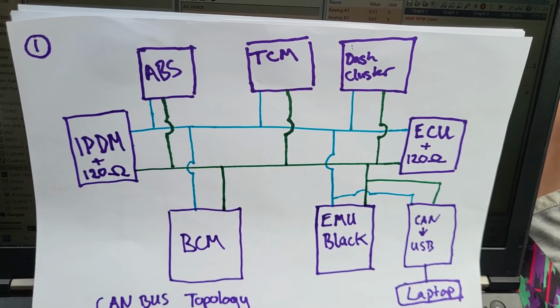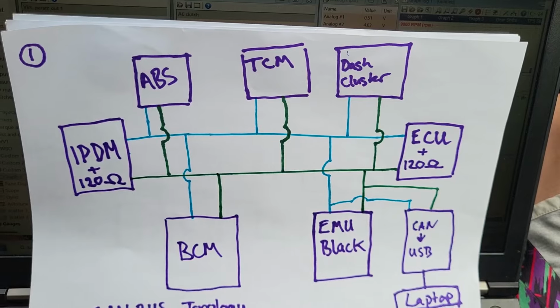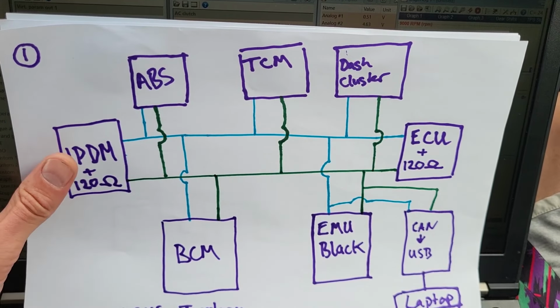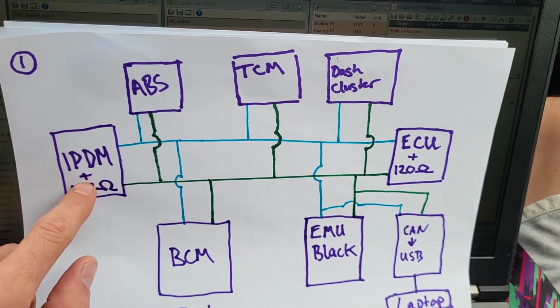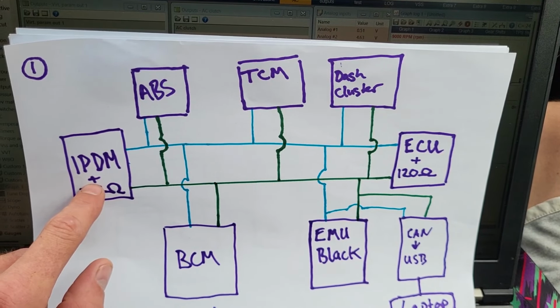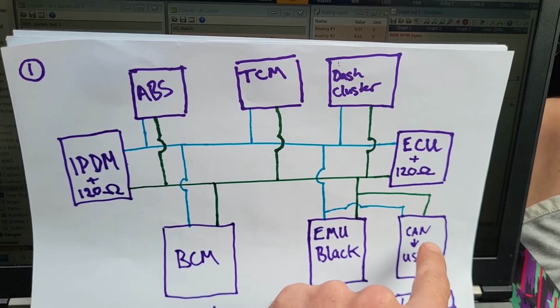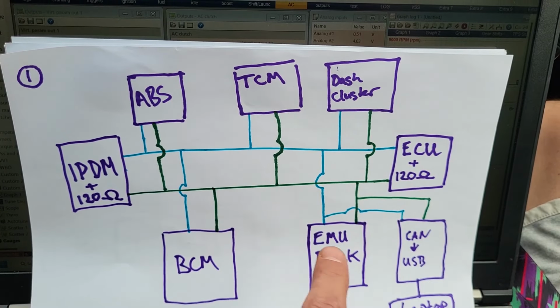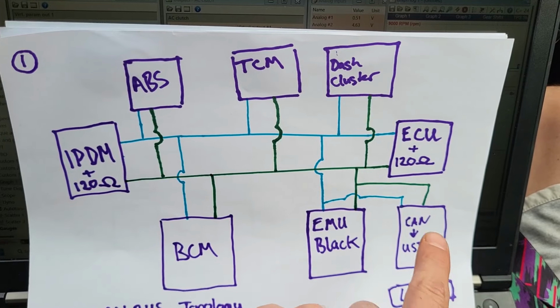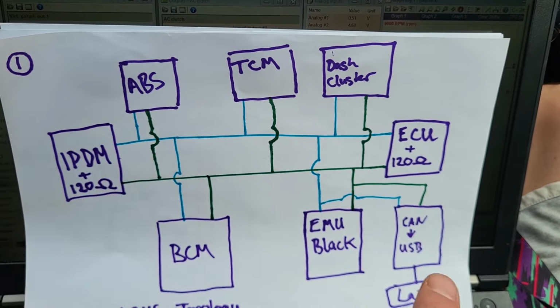This is what's existing here. This is already in the vehicle. Let's say we were setting up an ECU Master PDU, and it's the very first device on the CAN network. We're going to need a CAN to USB device. I'll talk more about that one in a minute. But in order to communicate from the laptop to that, forget all this other junk, we've just got 2 wires going from here to here.